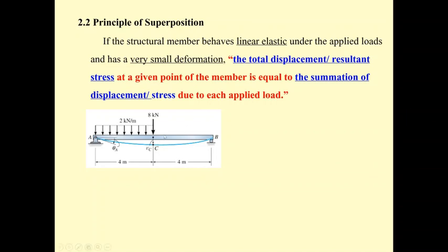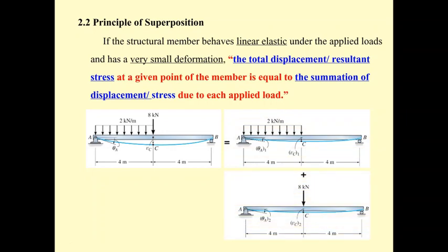And we limit the deflection to the length divided by 330 if there is a wall there. So for a 300 centimeter beam, we will limit the deflection to be only 1 centimeter. So most of our beams in civil engineering will have very small deflection and will behave in a linear elastic manner. And then we will separate this beam into two beams.